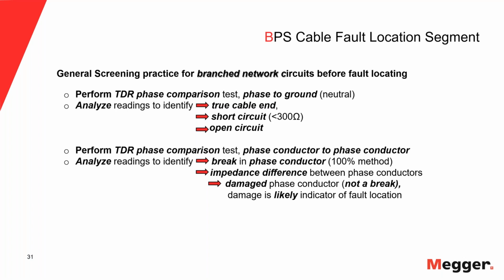That almost suggests that you have one spot where everything just completely blew up and is shorted out to each other. Okay. In the end, they went to the substation and they found, I think it's called a reactor, that was right in the substation that had caused a short circuit between all phases. So that's why I'm saying the insulation resistance reading gives you a good indication, and the fact that you can go from the substation can save you a lot of time.